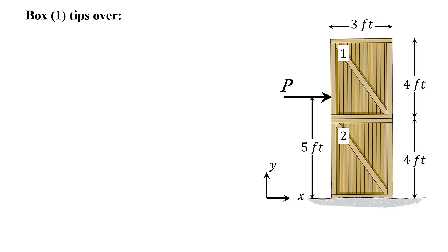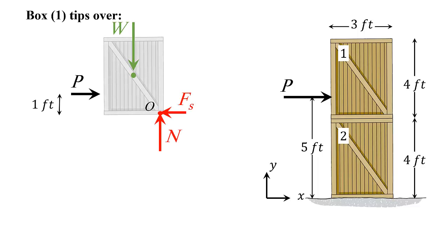Alright, now I have to put the N force at the edge because there is tip over, no movement, no sliding, and in this case, because there is tip over, I need to include the moment equation. But let's see how we can simplify things.